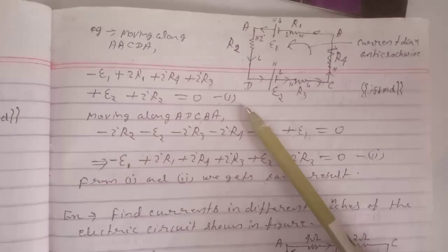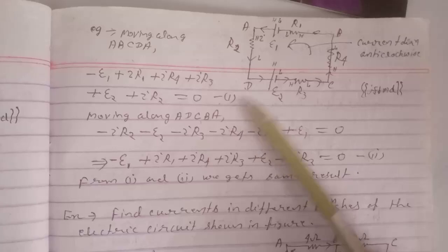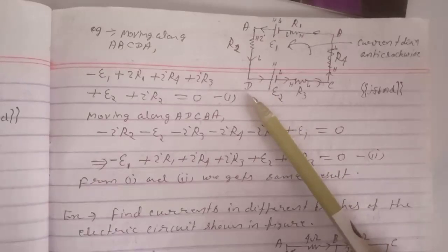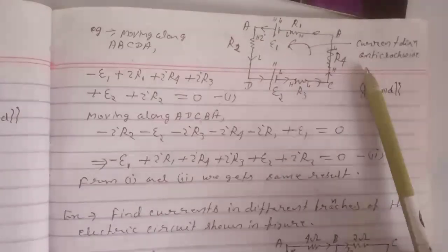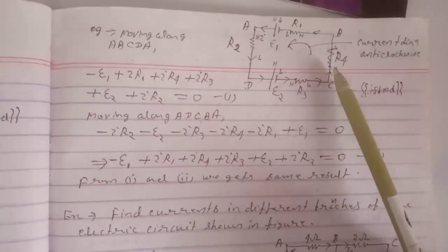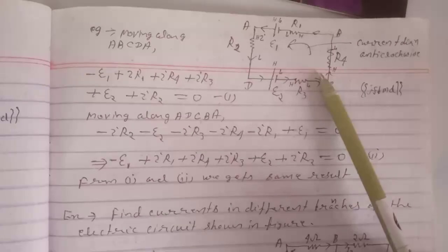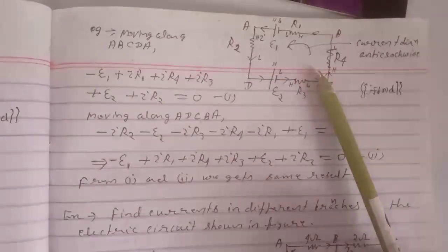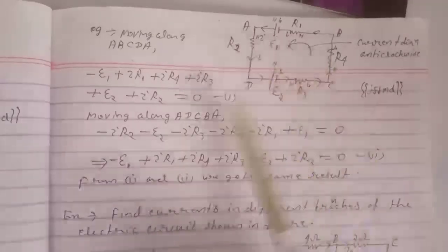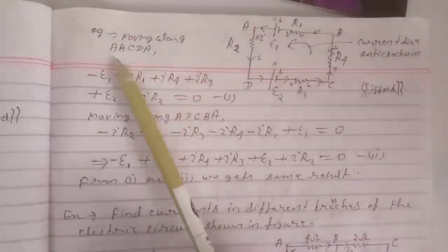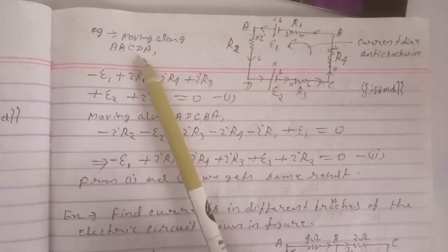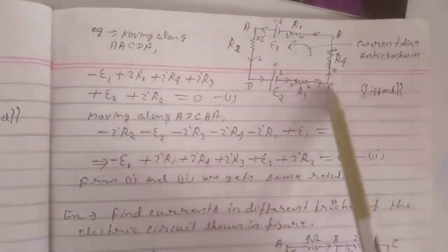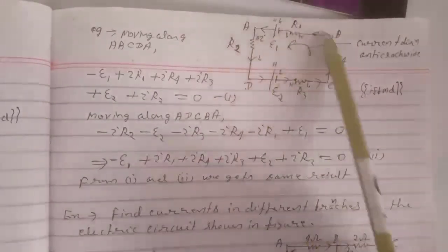We may also fix the clockwise direction, so we have to choose only one direction. The answer will be the same. So first, see what we get applying KVL after fixing the anti-clockwise direction. For example, moving along ABCDA, here we are moving in this direction, opposite to the current direction,